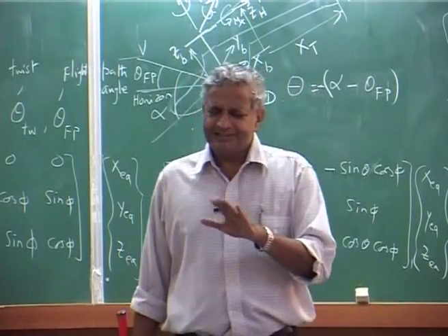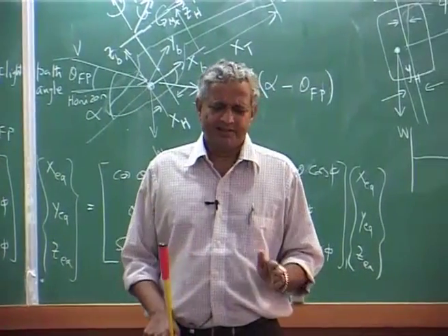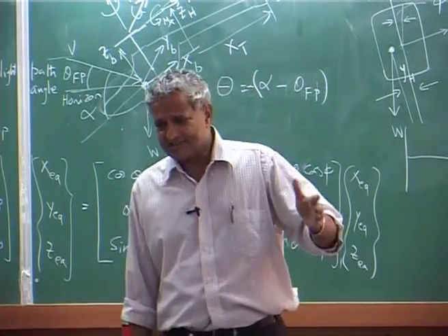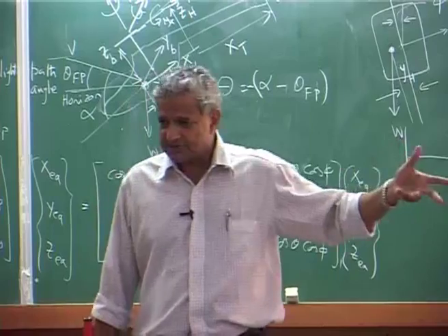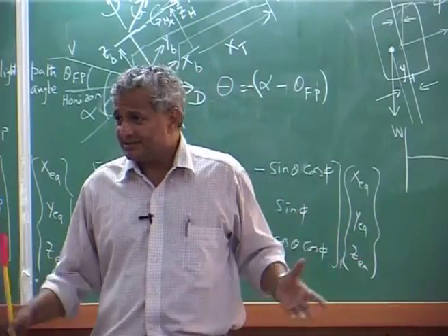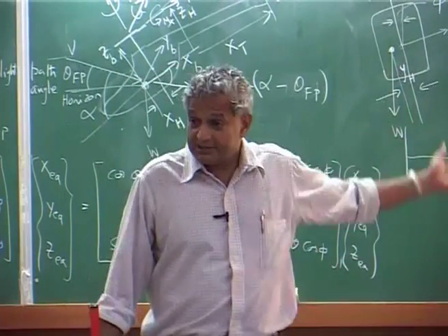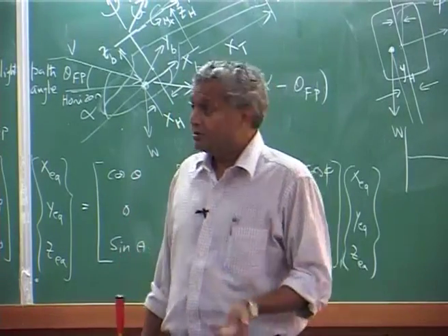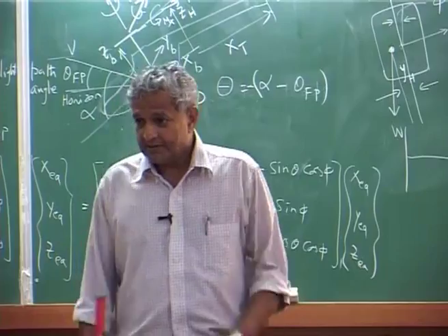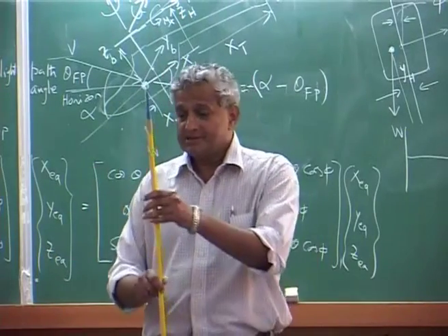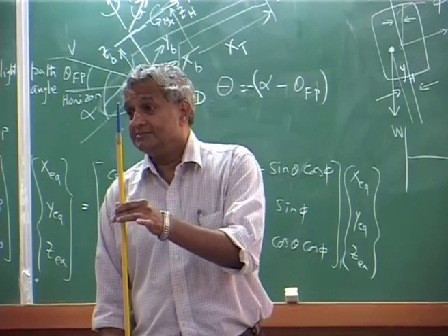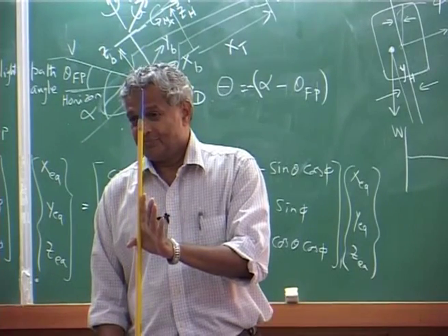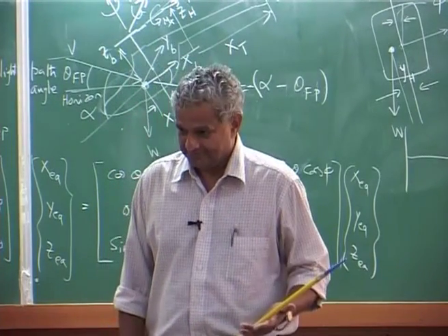But that is for a research publication where you want to study more about only blade response, blade characteristics, influence of certain geometry on the aeroelastic behavior. They do not do full analysis of the helicopter. Now, another aspect is you can do wind tunnel. In a wind tunnel, what happens is it is kept at a specific shaft angle. That means alpha is fixed. That is called a wind tunnel trim.